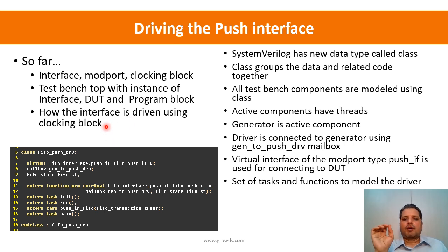Now we are going to expand the view a little bit further and look at the task that we saw in the previous slide where we were driving. Where is it located? This is the class for the FIFO push driver. SystemVerilog has a new data type called class, and a class groups your data and code together. All your testbench components are modeled using classes.